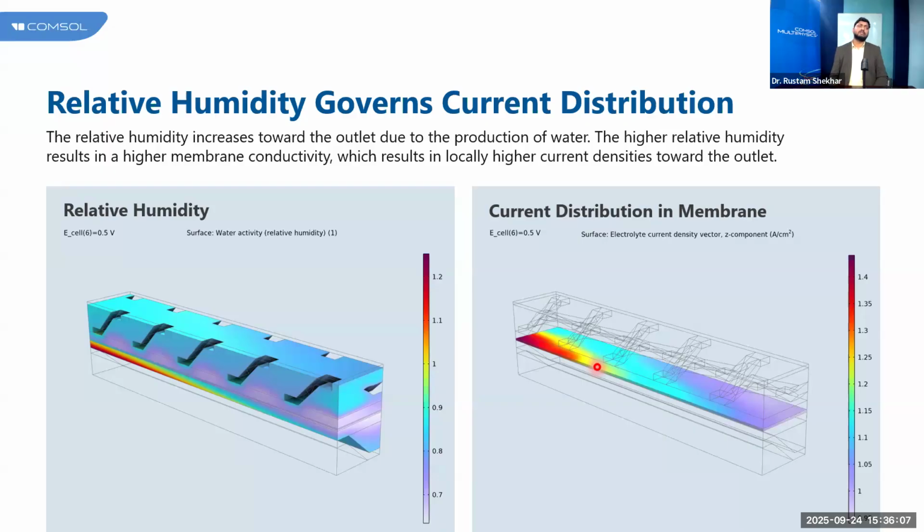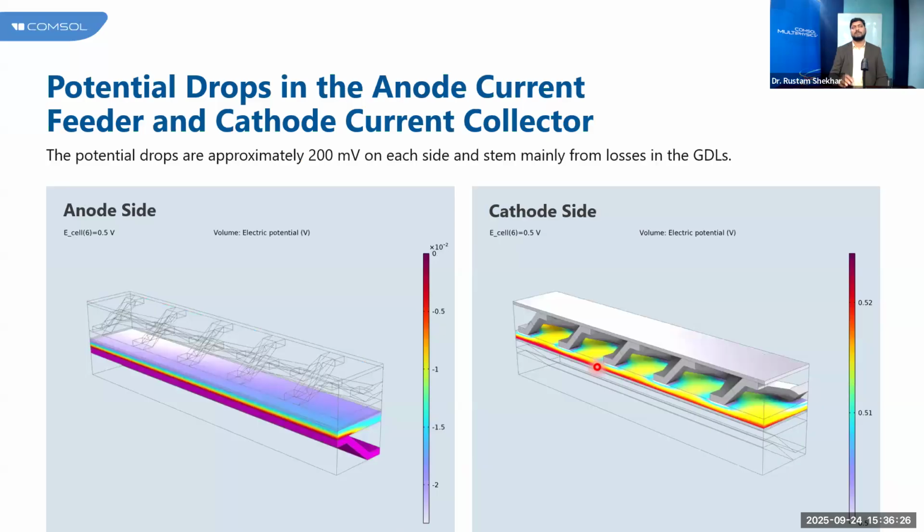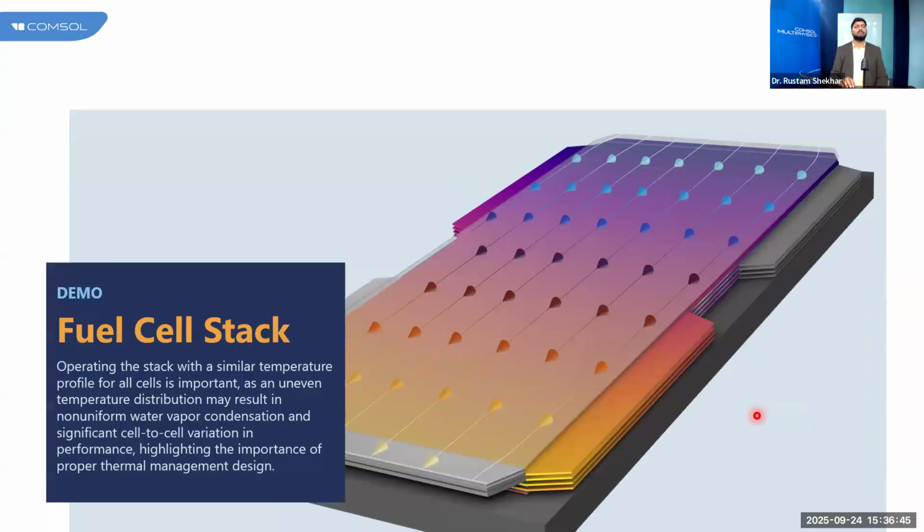So let's see or discuss these examples towards the automotive sector, because people deploy PEM fuel cells majority-wise in vehicles. In a vehicle, fuel cells can give you constant power, but the area of improvement will be as we discussed with the different examples. Here the cooling channels, how the membranes are associated, what the thicknesses of your electrodes will be, whether they will be mechanically stable, and what kind of losses we will obtain. All those things can be figured out by this.